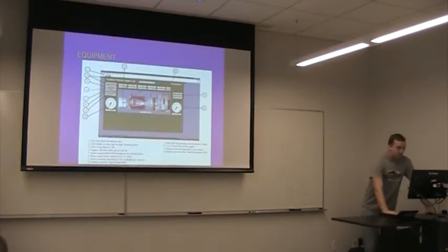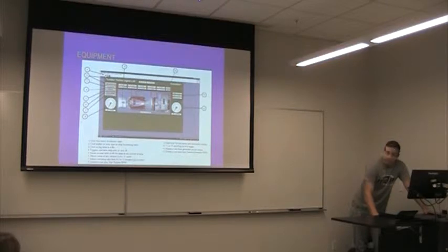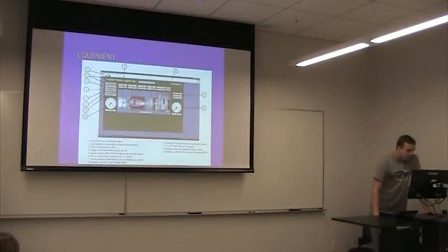So this is on the MyDAC screen. Kind of hard to read at the bottom. It's all the different things that we use. So right here is the monitor data. That's where you turn that on. It starts monitoring everything that the turbine's putting out. 2, you have 2 different options to click. This is a stop sign if it stops monitoring, or you can just hit stop monitoring right here.